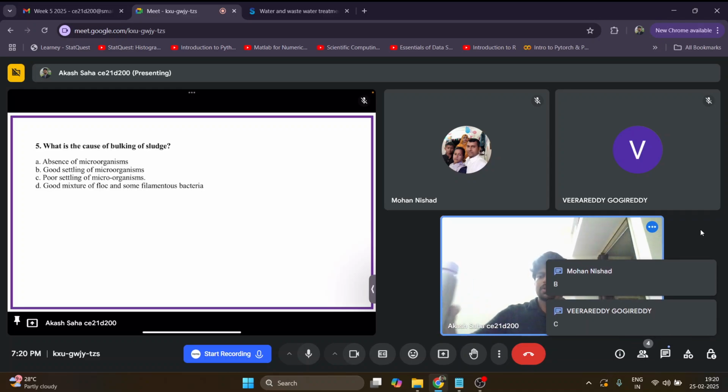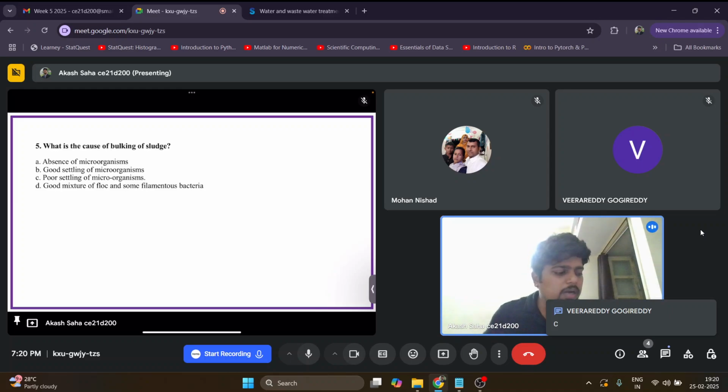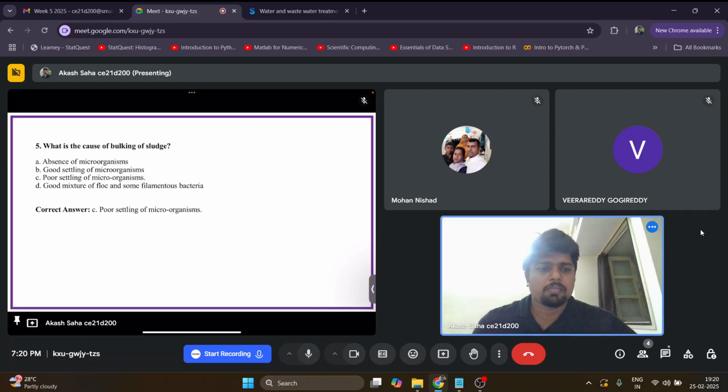Obviously, if it is a poor settling microorganism, then the sludge bulking will happen. So option C is correct. Direct question. Due to poor settling microorganism, the sludge bulking will happen.